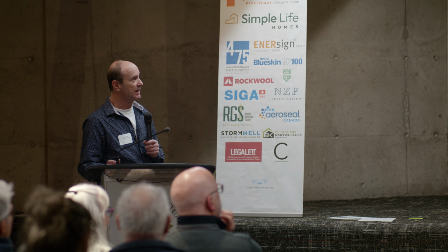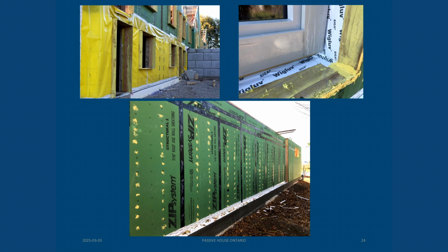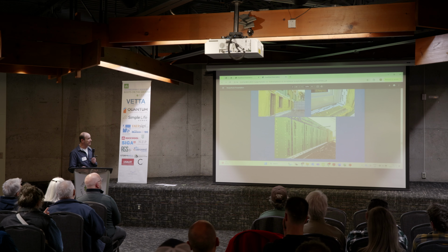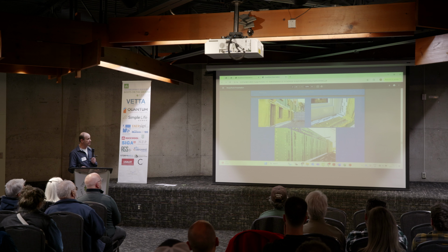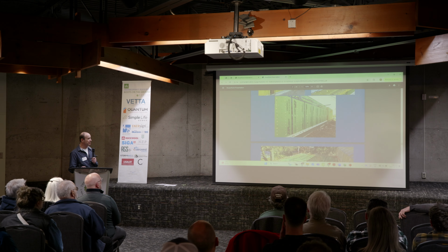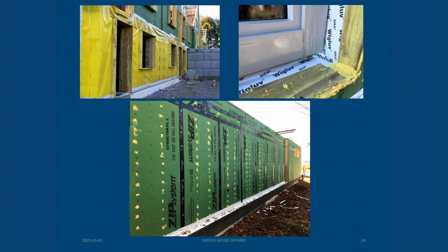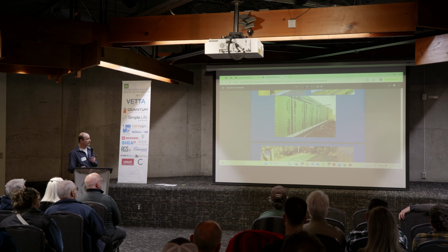It does. I mean, we didn't do a blower door test before to see how it was. Afterwards, we got really excellent airtightness. But anyways, if you're going to go through the process of putting a lot of effort and attention to all these other details, it's really not that much to do this last little bit. It was only on, I think, 2 faces of this foundation wall. This is just an example of the air barrier layer again before the exterior insulation is installed.